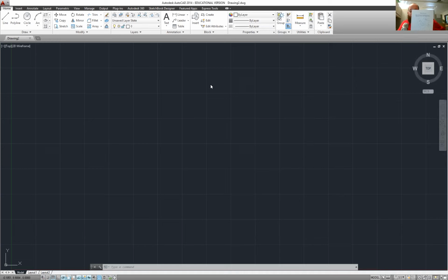To start this drawing, we're going to create this spine that goes through the center of this drawing. So I'm going to begin here by selecting the line function. When I do this, I'm just going to come down here and click. Oh, looks like I didn't get it selected. Click on the line function. Okay. Then you can see that dotted green line that extends above the line there. It's because I have the snap on, and that helps keep the lines vertical or horizontal.